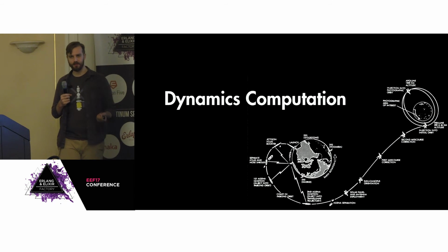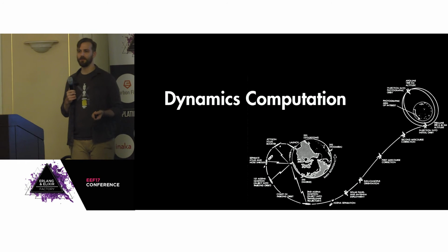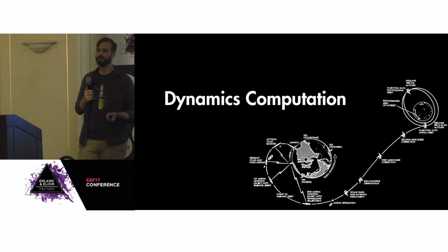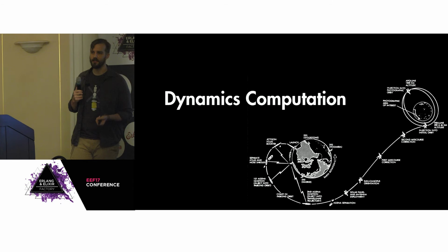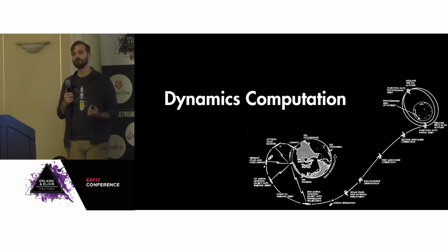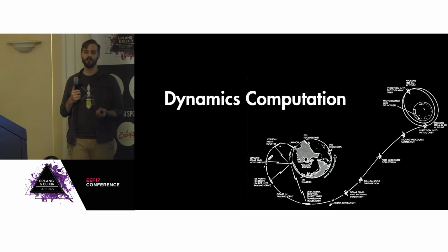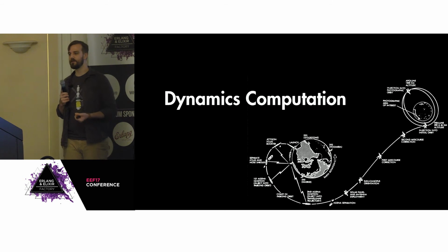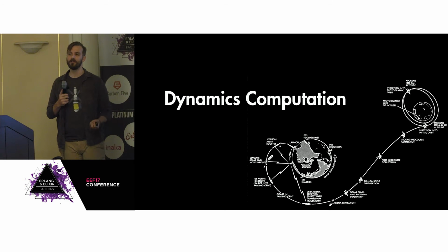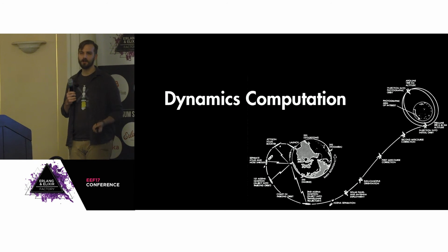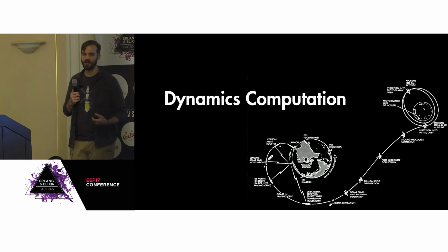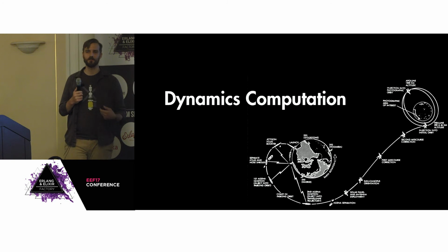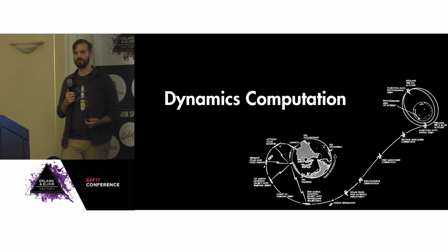You also have to be able to do dynamics computation. So you have to be able to do number crunching. You can build a special purpose ASIC to do these things for you, but that draws power. So maybe you want to use spare cycles in the general purpose computer to do these computations, which is what almost everybody does. The space shuttle had special purpose hardware inside of the GPC to facilitate orbital computation. The GPC was the general purpose computer for the shuttle. We now just call those floating point units.